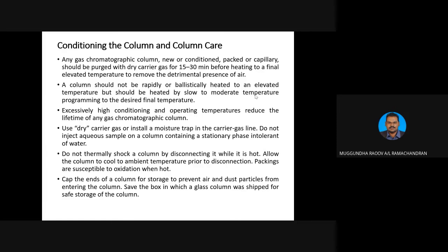A column should not be rapidly heated to the elevated temperature, but should be heated slowly to moderate temperature by using temperature programming to the desired temperature. So basically, we can't heat it up directly. The temperature should gradually increase. Please take note of this.